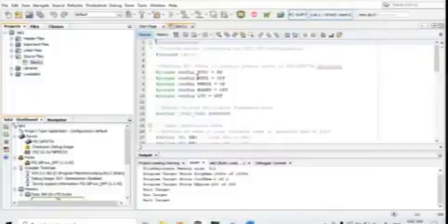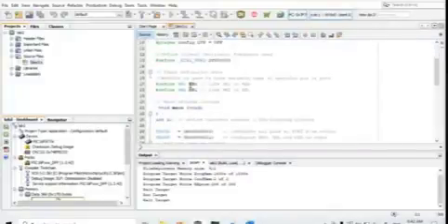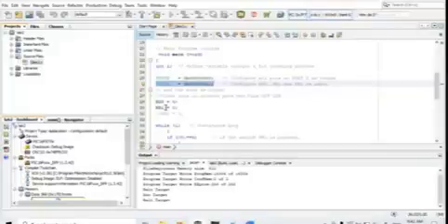The configuration still remains the same, with 20 megahertz, and the inputs RB0 and RB1, and then accept this one. We are using port D as output, so we need to configure TRISD as output, and the rest remain the same. For TRISB, it is similar to the previous one. We are using only two inputs, so the inputs should be at RB0 and RB1, and then we clear any initial value from port D, starting with RD0 and then RD1.